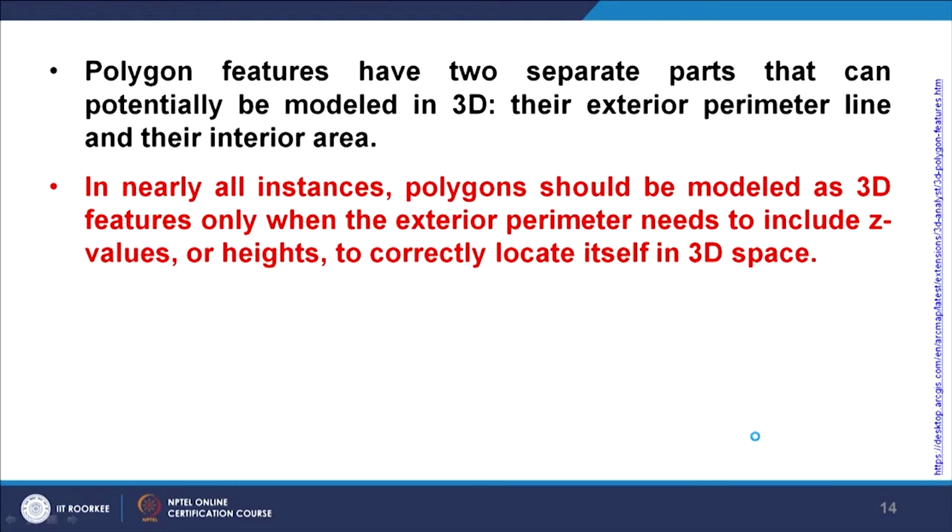But if a plot or an agricultural land has undulations, then against that plot only one single Z value will be stored. And in the real world, there are undulations. So, if you want to store undulations, you have to have separate polygons, or there is another way of representing such a thing: go and resort to raster data rather than vector or polygon data.